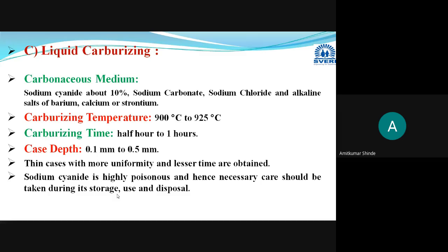Now the temperature used to perform this carburizing process is approximately 900 degrees Celsius to 925 degrees Celsius, and this process requires 30 minutes to 1 hour. At the end, the case depth achieved can be from 0.1 millimeter to 0.5 millimeter. So this is the liquid carburizing process.